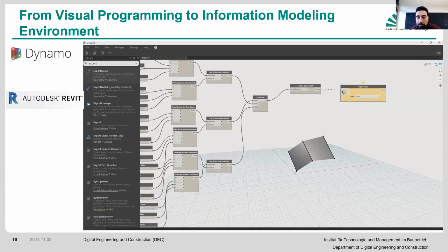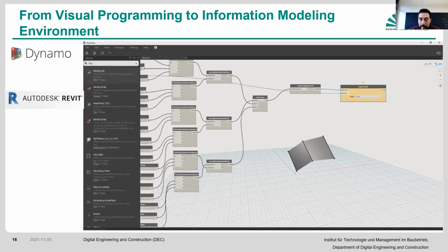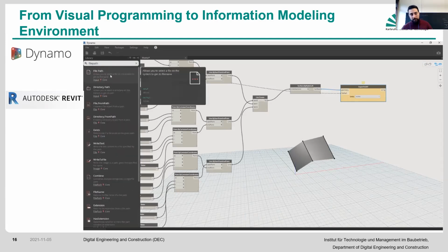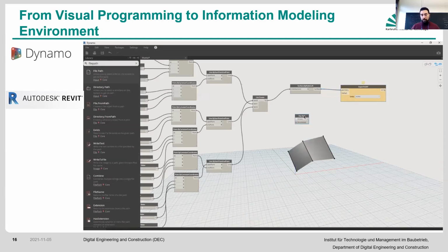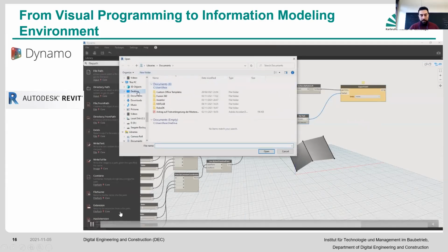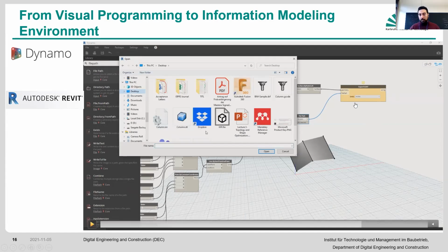And this is where you can actually create some sort of essentially unit. So imagine you have modeled your column or whatever it is. Now you want to export it to another software that requires, let's say, an SAT file or an STL file and these types of things. SAT and STL are essentially triangulation files. Every surface is represented by a set of triangular meshes that provide that. And then here, the two things that particular function requires are the geometry and then the file path.